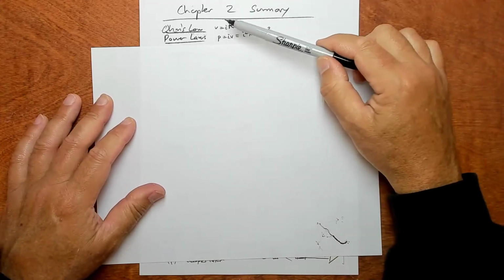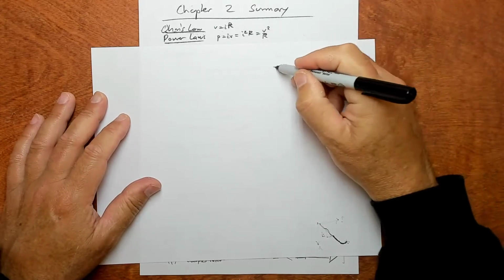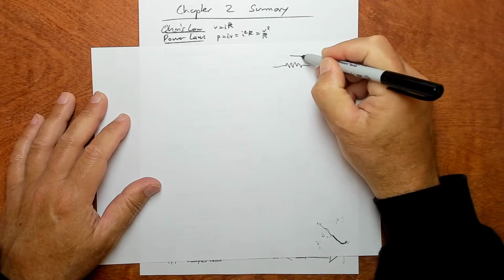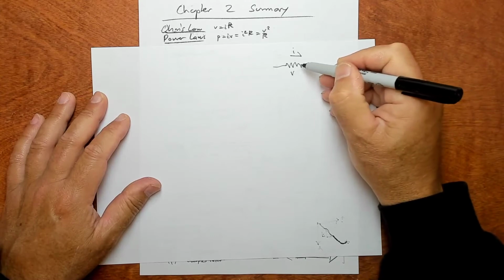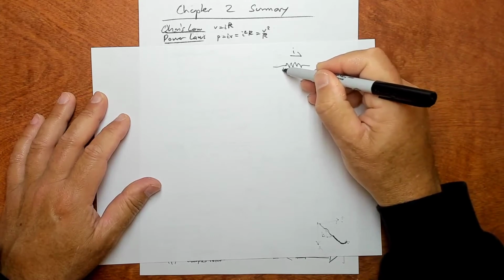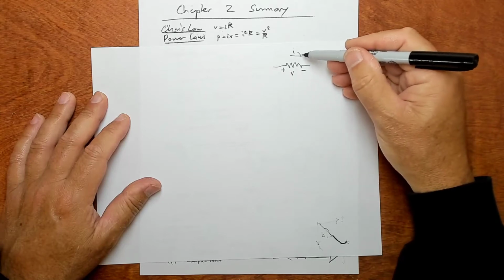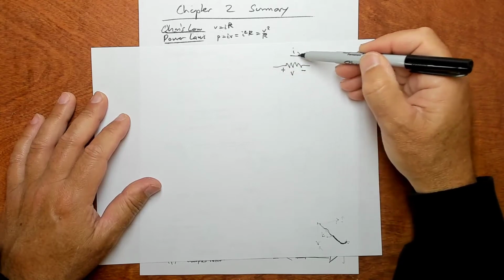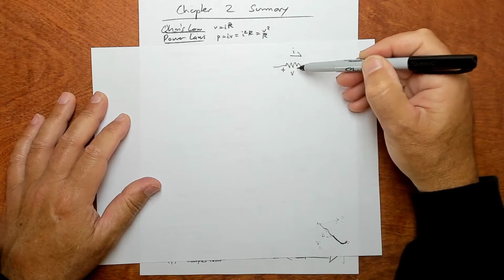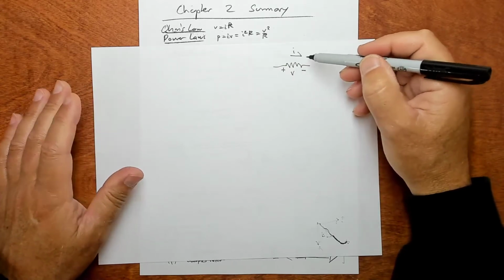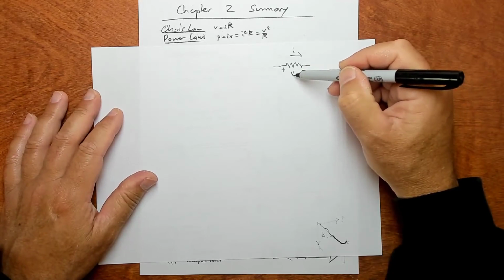So Ohm's law is V equals IR. So it's saying the voltage drop in a resistor. So you've got a resistor, you've got a current going through it, I, and then you've got a voltage drop across this resistor, and the polarity of the voltage drop will be this direction relative to the current. So the plus is always at the entry point of the current. So the resistor is resisting the flow of current, and it does that by producing a voltage.